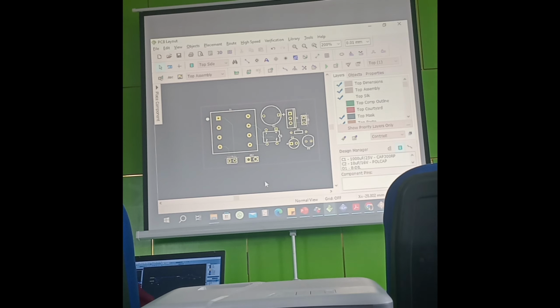For this type of design routing, you can't make use of two-side routing, just one side. When you have less than 20 components, I don't expect you to use double-sided. If you have components below 20, you should be able to arrange the components in such a way that you route it in just one side.